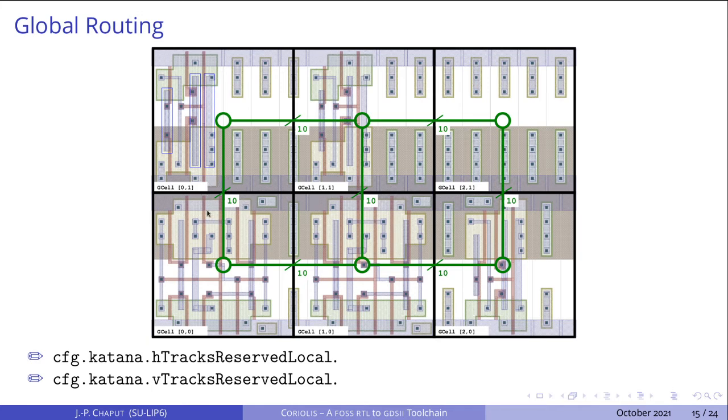So obviously, it will make the work of the global router more difficult, but it eases the one of the detailed router. So it's a trade-off. And it's a trade-off that you may have to change for each design. Maybe in the future, I can make the router better, so it can more smartly guess that number itself. But for now, you have to do it yourself.